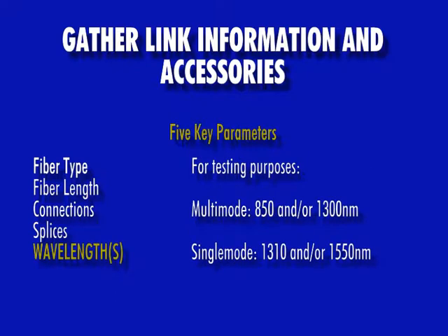Lastly, the user must determine what wavelengths they will test at. For multimode, this is 850 and/or 1300 nanometers, and for single mode, this is 1310 and/or 1550 nanometers.